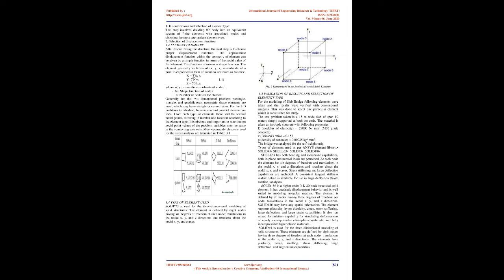1.2 Objective of this research paper. The main purpose of this research is to develop an FEM model using software ANSYS for analysis of skew slab bridges for various I.R.C. loading conditions, and to analyze single lane, double lane, and 4-lane skew slab bridges for various spans, from 6.0 m to 10.0 m span, and for various skew angles, from 0 degrees to 60 degrees, and to obtain the final design forces.